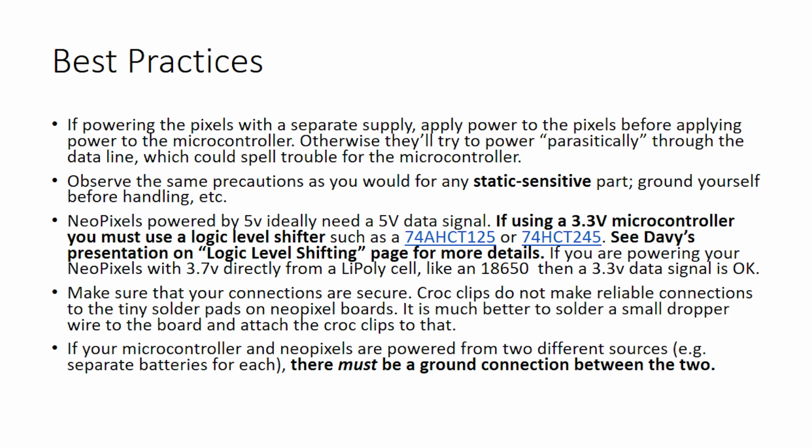But it's a good practice when you're writing code to write at the start of your program, make everything an input until you're all set up, and then give it half a second, delay 500, and then you know that all your electronics is stable, and then you apply the outputs and start sending ones and zeros out to your lights and your motors and your actuators and all that stuff. And that's good practice, and it's particularly good practice with NeoPixels, because if a pin comes up that's an output and the NeoPixel hasn't had energy yet, it'll try and take that power and it'll damage the controller.